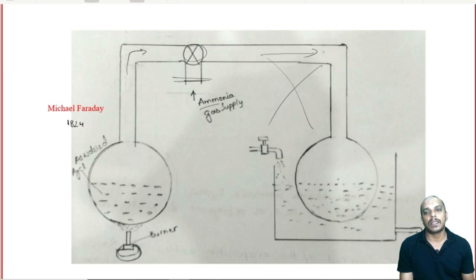If we heat it, the ammonia in gaseous form, which is at higher pressure and temperature, will go to the other side of this experimental setup where it is cooled. We have some cooling mechanism, maybe liquid water or something. If we cool this, the ammonia gas which was separated can be liquefied. So, what we have obtained is ammonia in its liquid form.